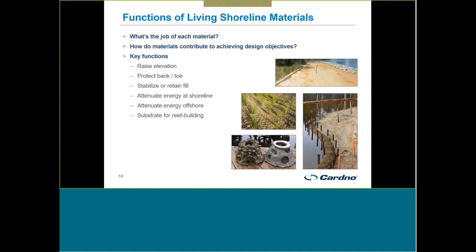They're going to help stabilize or retain fill material that may be placed along the shoreline. Energy attenuation is a key function of a lot of these different materials, whether that happens right at the shoreline or a little further offshore, like some of those pictures I showed a few slides ago. And then for those projects focused more on ecological uplift, along with some wave attenuation benefits, the materials are really more of a substrate or a scaffolding for reef building organisms. So you've got a biological component ultimately, but it starts out with some hard substrate for colonization.